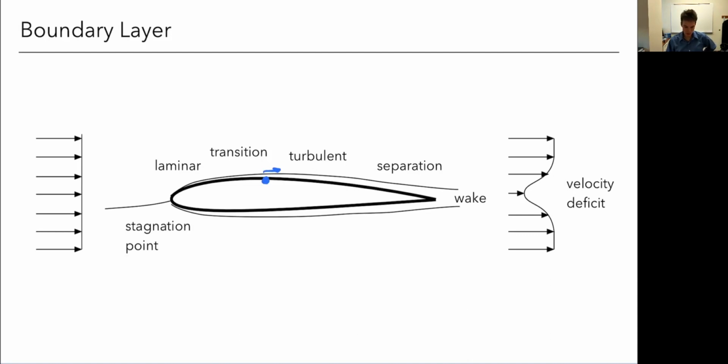From this picture, we notice two types of drag. One is a pressure drag. These are names we'll give to it, or profile drag, I guess is a better name. And this is due to the momentum deficit. So if we look here up at the free stream, the flow is all uniform. If at the back edge it was also of the same magnitude uniform, there would be no drag. But because we have this deficit here, some momentum has been lost, energy has been taken out of the fluid, there must be a drag. Conversely, if there was an increase in velocity, we would know that we had a thrust producing device upstream, right? So there's this profile drag.